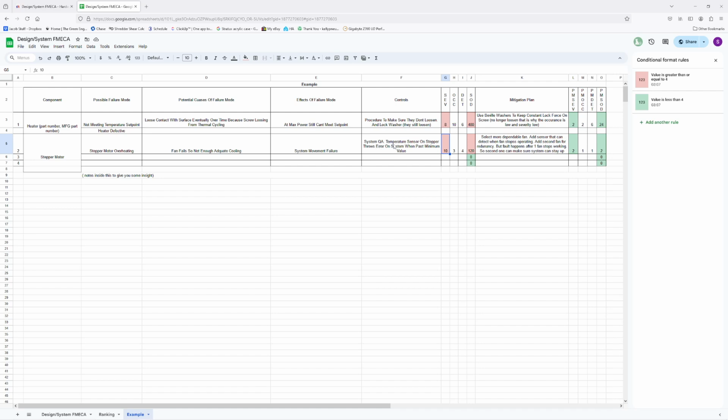System QA. So okay, test it first in your lab. Again, you're running marathons. You should be able to catch this, right? Run your heater at the max. Also, generally in your specifications, you have an environment that you have the machine in. Generally, the normal environment of 0 to 50C is pretty standard. So you put it in an environment inside an oven that's set to 50C and it runs. Does it run? Yes. Can you run a marathon with it? Does it continue running? Yes. Okay, most likely no problem.